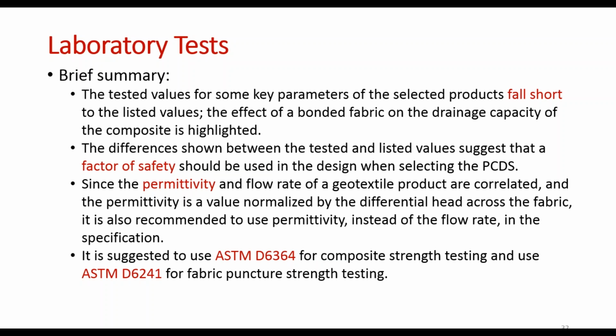And also, since the permittivity and the flow rate of the geotextile products are related, but they are both listed in the manufacturer product database, we suggest using permittivity only when we design the specification.